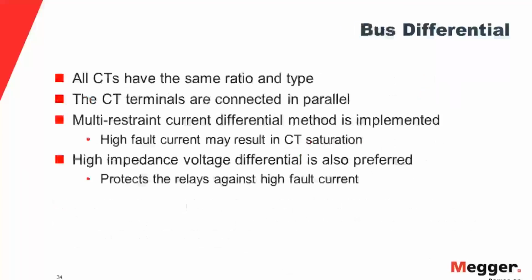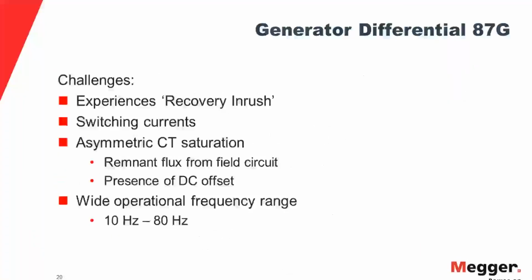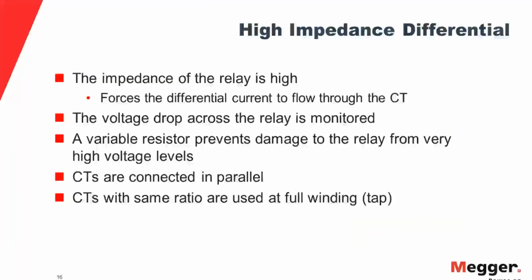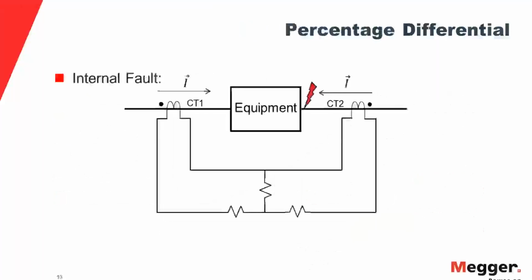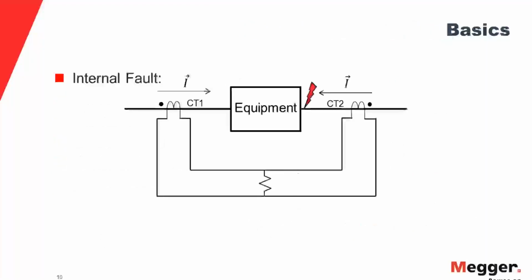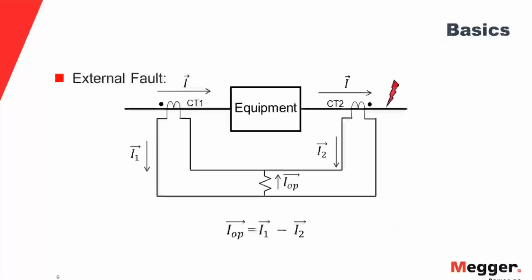Okay, can you hear me all right, sir? Yeah. Loud and clear. Okay, so bus differential faults are extremely rare, and probably you won't see but a handful in your career, but the potential for extremely high damaging current is extreme. So they have to be taken extremely seriously, because if a bus differential fault is not cleared, it would be extremely damaging on the system. So it's highly advisable to implement bus differential protection and hope you never need it. I think that solves that one.